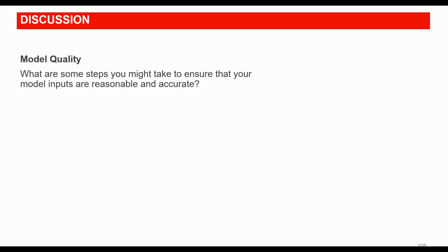For example, on an envelope input, if you calculated a detailed U value, make sure that what is coming out of the model is actually showing the correct U value that you've calculated. Other things: compare to previous models you've done, benchmarks, look at CBECS, for example. But again, keeping track of what you've put into the model is very important, where the data came from, because it'll help you go back when there are questions to be able to answer those questions.